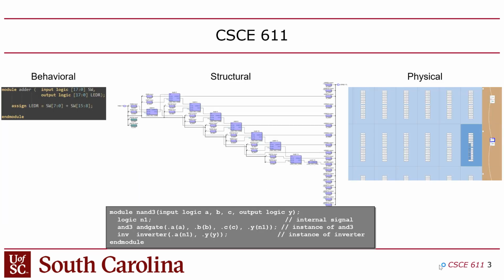And in this class, we're going to be doing the same thing as you did in 211, except they're going to look a little differently. The behavioral description is going to be in SystemVerilog, which is a high-level programming language. Now you can define Boolean logic very easily, very naturally in SystemVerilog, but you can do more complex things in there as well.